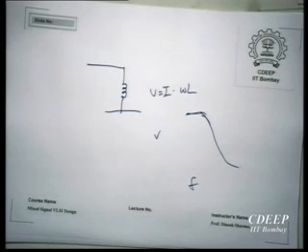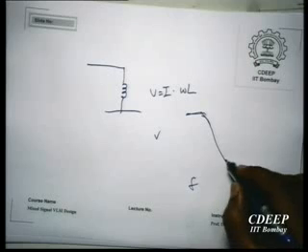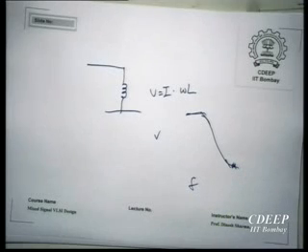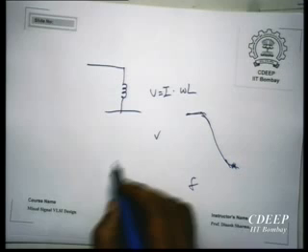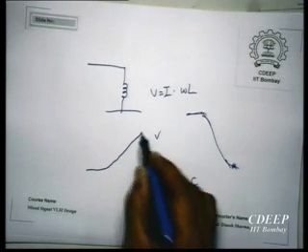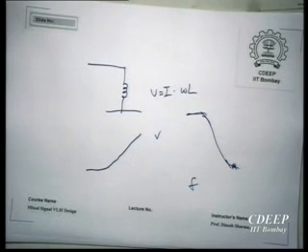So if the line is like this, I need, okay, in fact it is not like this, it just continues to come down, right? First pass, first pole, one pole, single pole system. So really what I need is a system whose transfer function is like this, so that when I take the product of the two, I will get a constant with frequency.